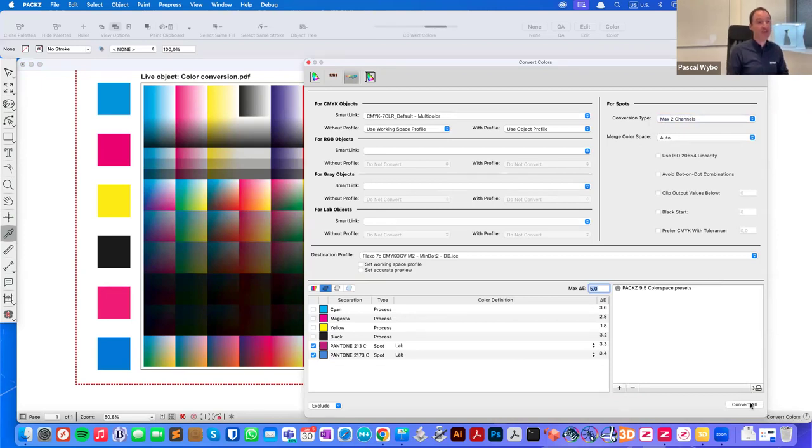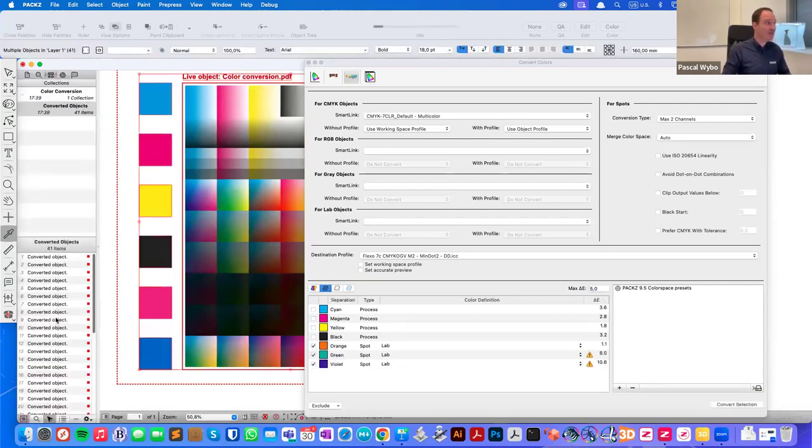And when everything is done, you simply have to click the convert all, and the magic happens in an automatic way. And when everything is ready, I would be able to measure the color conversion as well. That will take some seconds. It is done. It's going to give you a summary of which objects have been influenced. But here, I keep it now with my spot colors. There are only 2 colors used for bluish. There is no black in it because I explicitly asked through the spot color refinement to only have 2 channels in it.